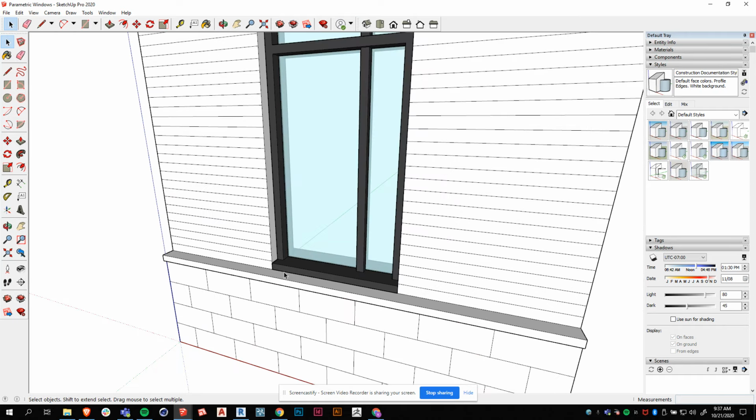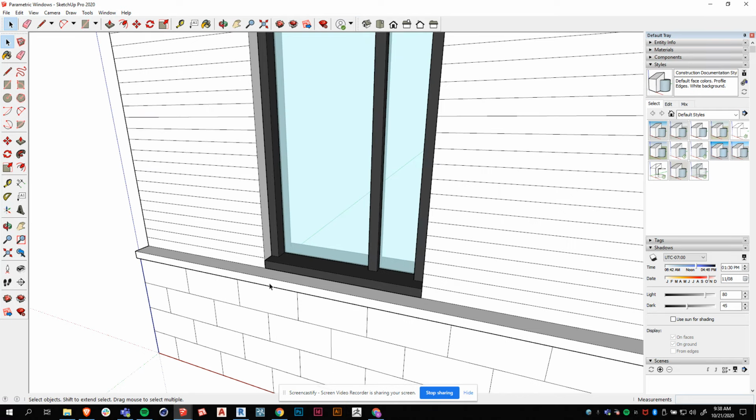Now, there's a couple ways we could draw it. One way we could draw it is I'm going to draw, say, line work on the sill reference plane and then extrude it up some height. So I can make the height of the box that I draw down here a parameter. I could say, hey, make it this high. Now, there's some other interesting parameters that you could add here. How far out does the sill come on the interior? How far out does the sill go out on the exterior? Those would be 2 good ones to add as well.